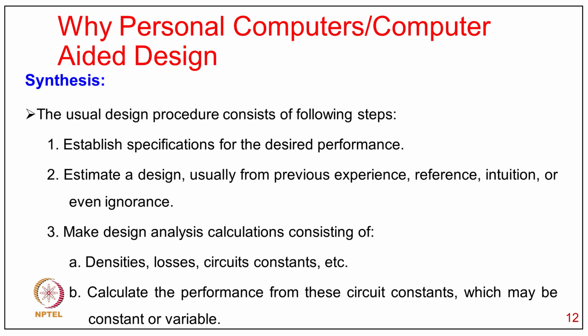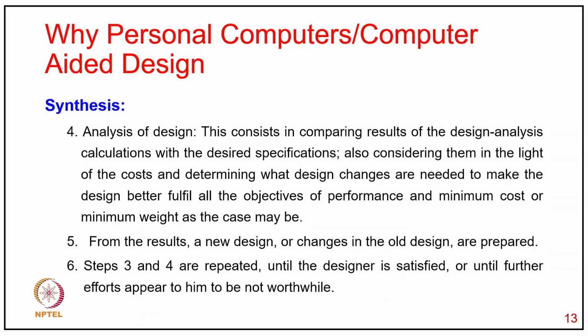The usual design procedure of synthesis consists of the following steps: establish the specification for the desired performance, estimate a design usually from previous experience, reference, intuition or even ignorance, and make design analysis calculations consisting of densities, losses, circuit constants, etc., and calculate the performance from these circuit constants, which may be constant or variable.